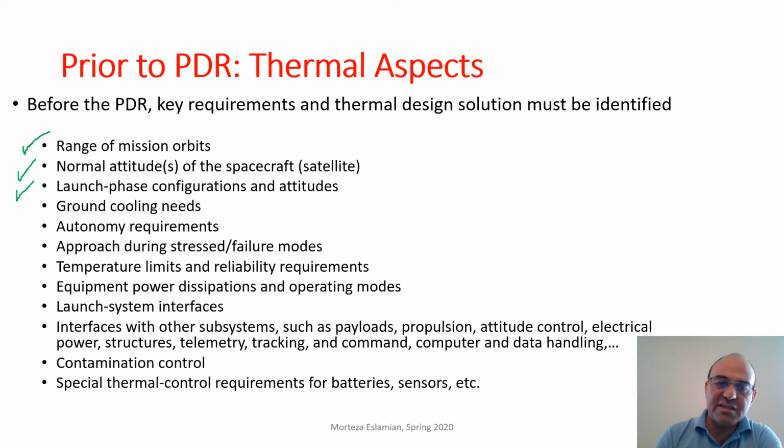Ground cooling needs, whether it needs to be cooled or kept at the right temperature when it's on the ground, and some other aspects like failure, so how to approach the problem during failure. Temperature limits for different components, reliability requirements have to be defined, equipment power dissipations and operating modes.